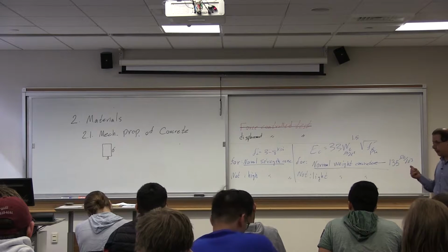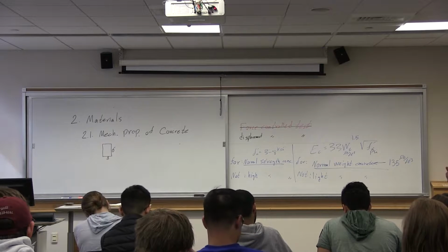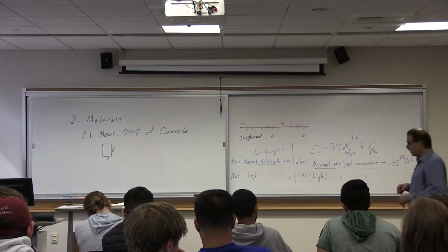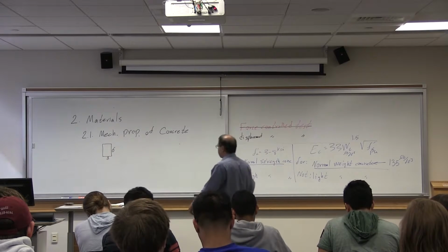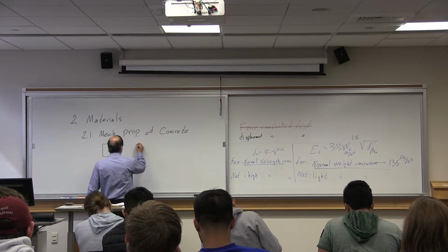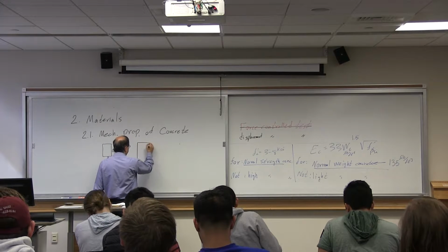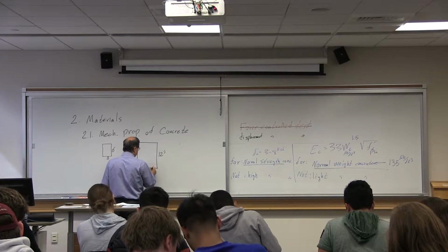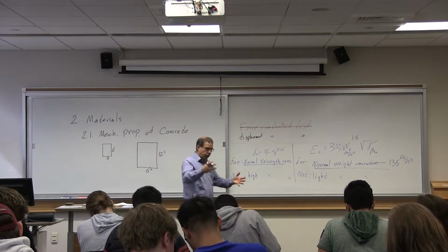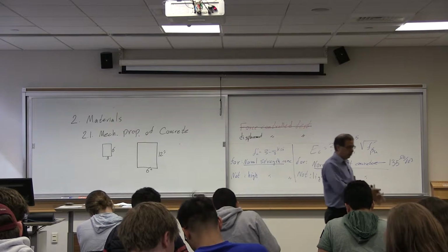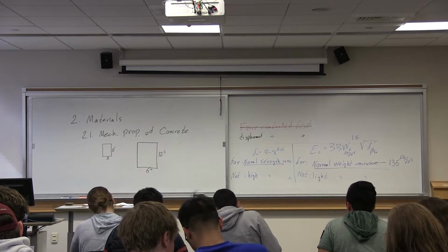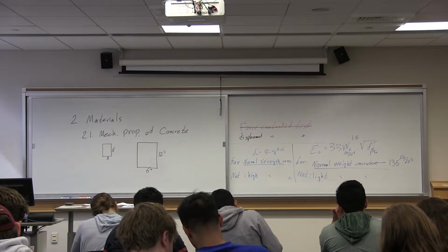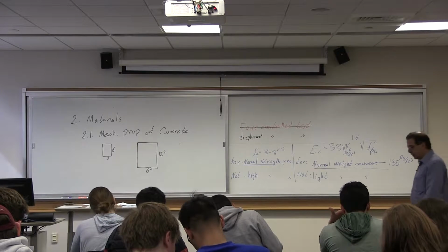But a 3 by 6 sample is not a standard sample. In the industry, you cannot use this one. The standard sample is a 6 by 12. So this is the standard sample, much larger and heavier. It takes some effort to carry it. This is the standard sample, 6 inches by 12 inches.